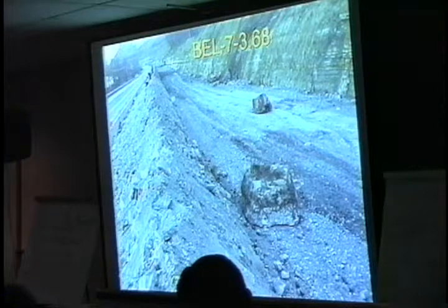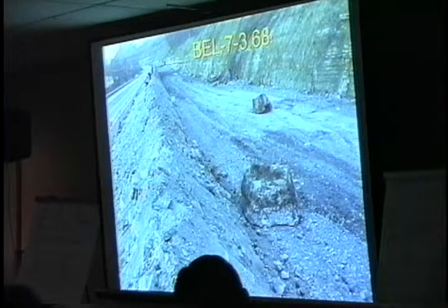We also did a groundwater study to find out if we could actually unload the top part of the slide by dewatering it, and with pump tests we decided that we just simply couldn't pump enough water out to unload it that way. So drainage was considered. What seemed to be most feasible at the time was relocation. You can see the road's at this alignment right now, and we're moving it over to this alignment. There's not enough time in the day to talk about all of the situations in this project, so I'm just going to leave it at that as an example of relocation.